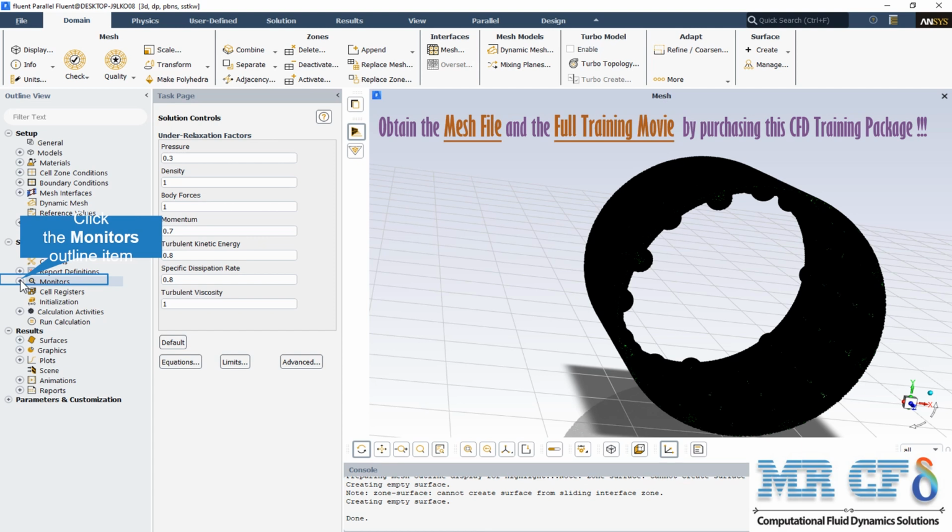A cautious approach is to save a data file before making any change to the under-relaxation factors and to give the solution algorithm a few iterations to adjust to the new parameters. Typically, an increase in the under-relaxation factors brings about a slight increase in the residuals, but these increases usually disappear as the solution progresses. If the residuals jumped by a few orders of magnitude, you should consider halting the calculation and returning to the last good data file saved.